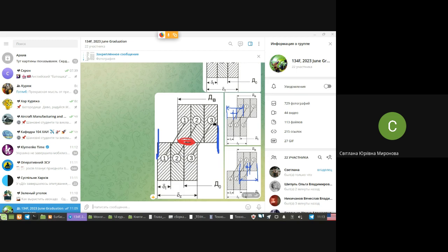of gauges for this side and for that side, if you have 3 groups, you need 2 gauges for each side. No? Instead of a couple of gauges for the shaft and a couple of gauges for the hole, in this case you need 6 gauges for both of these parts.